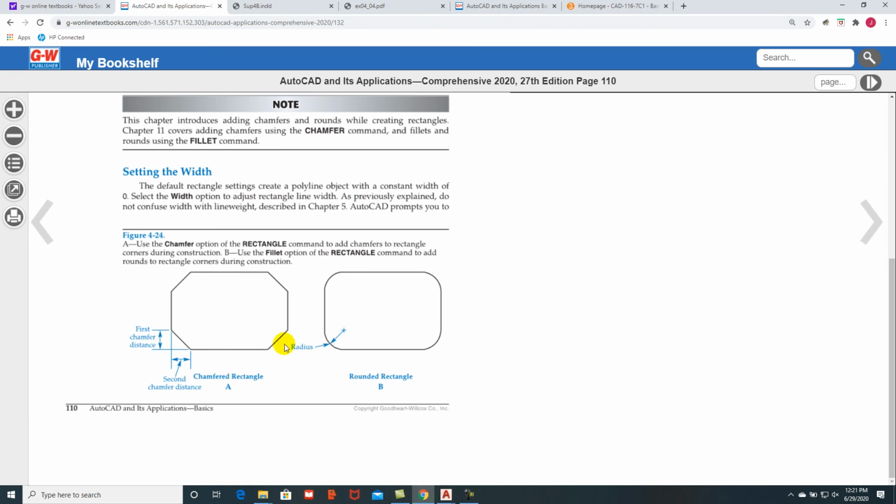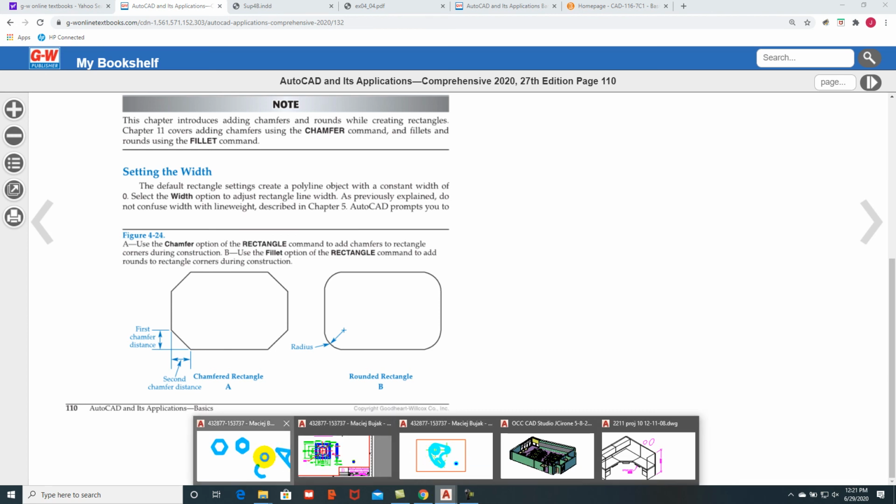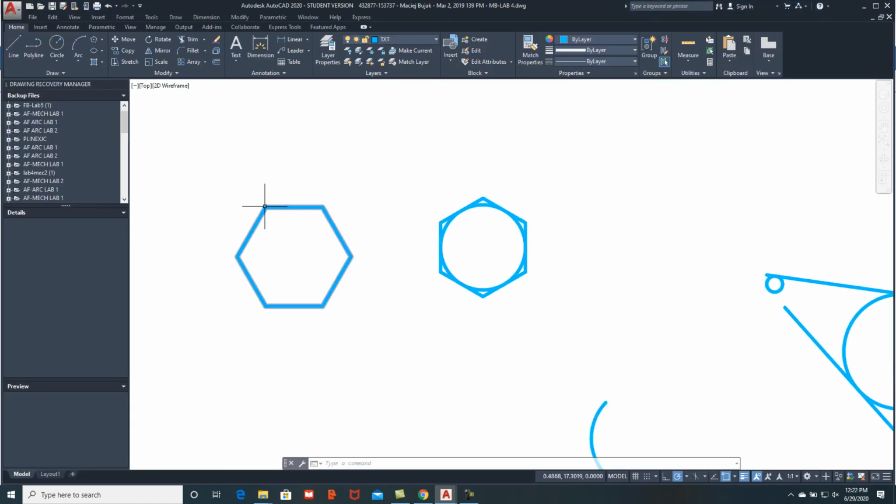And then you can put radiuses on other polygons automatically, and so it's a way of putting a fillet on by selecting polygons. So if I come back here to my geometry and I say, oh, this is actually a polyline, but if I wanted to say fillet, I'm just going to type it in sometimes. And then I'll come down here and I'll say radius, and I'll say 0.05, enter.